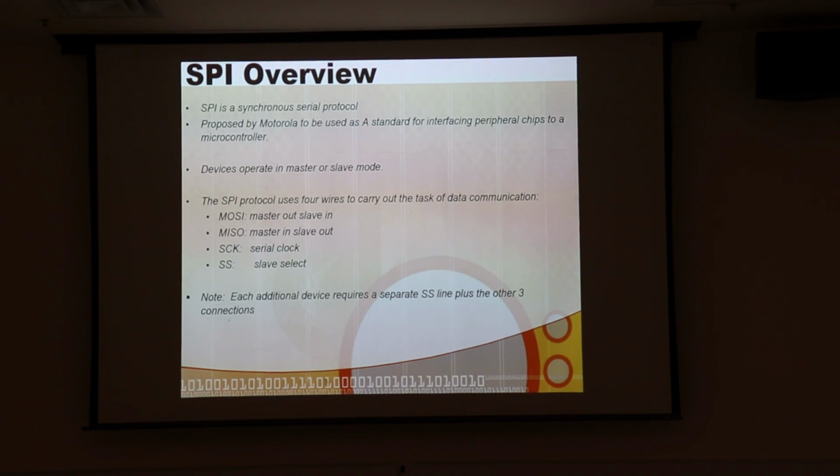And it turns out the slave select is not necessarily controlled by the module itself. Usually, your software has to handle the slave select lines on its own. So some of the things that would be taken care of automatically in the I squared C world, you have to do maybe somewhat manually in the SPI world.